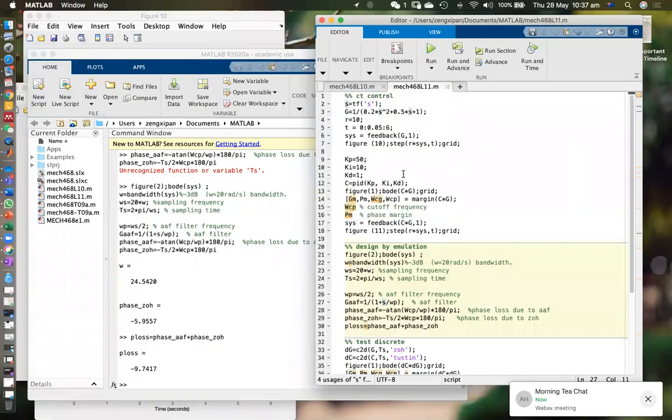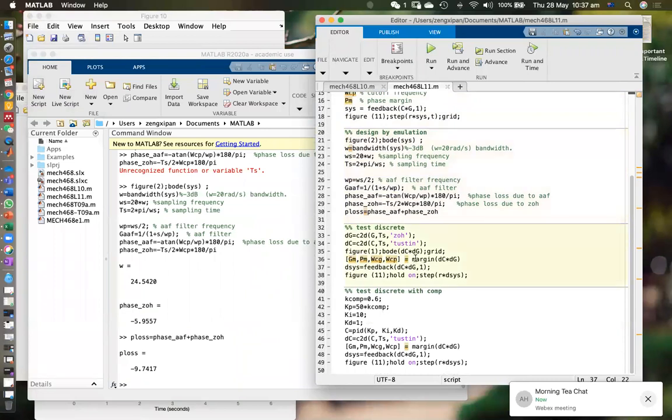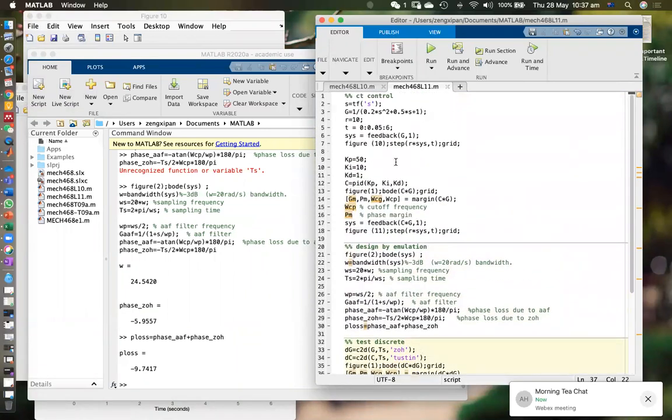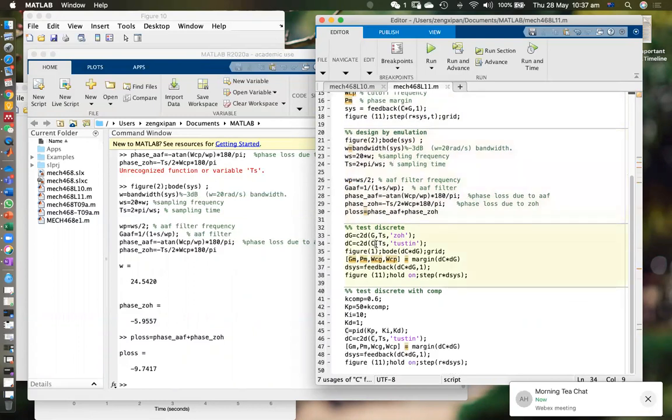The difference for you guys is this first one, continuous time control. You have a different model and a different controller. Everybody will have these things different, but from this going on, you're pretty much doing the same thing. So let's continue. We have a continuous time controller with 26-degree phase margin, and we digitalize it and realize we're going to lose 10 degrees. Now let's see what those 10 degrees mean to us.